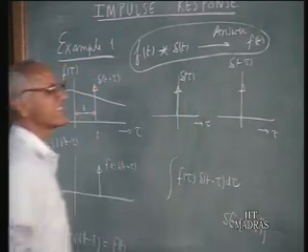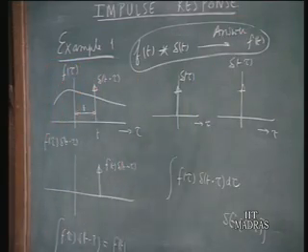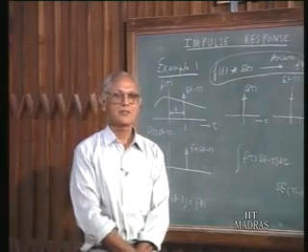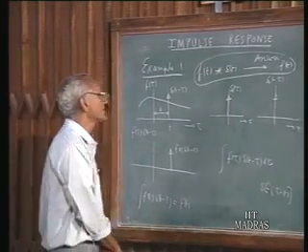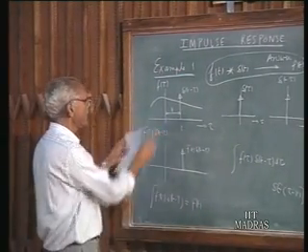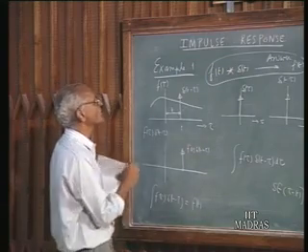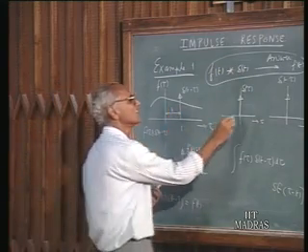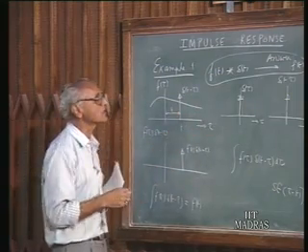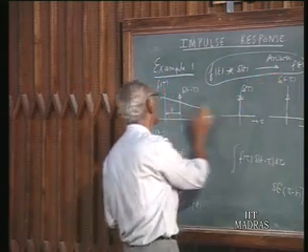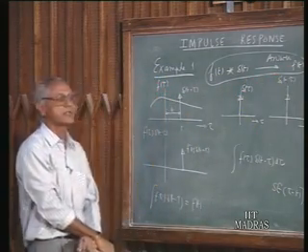This is a very interesting result, that the delta function when it is convolved with any time function yields the same time function identically without any change. Of course you may not have delta in practice, but if you have a narrow slit, for example instead of a delta function, suppose you are having a small slit like this and you do the same convolution, then you get an output which is very closely resembling this f of t.